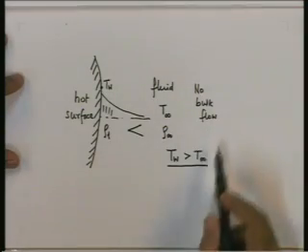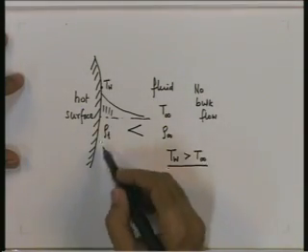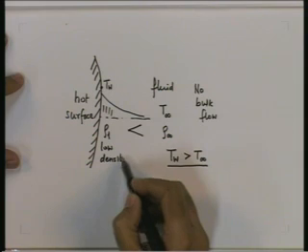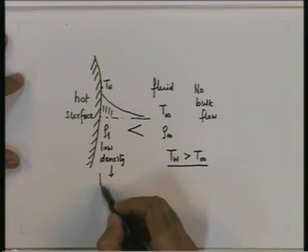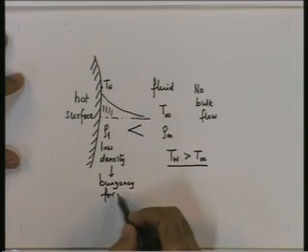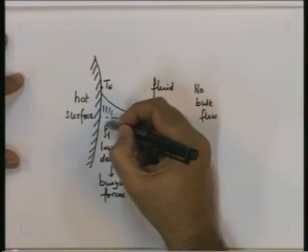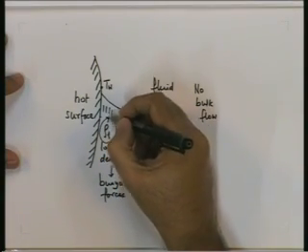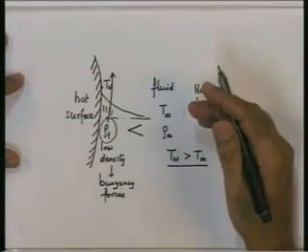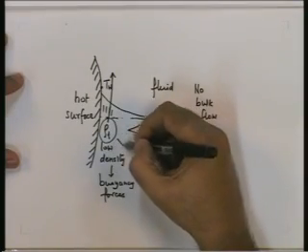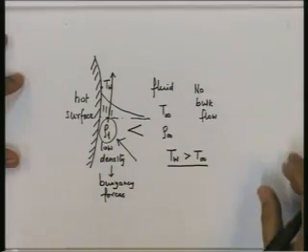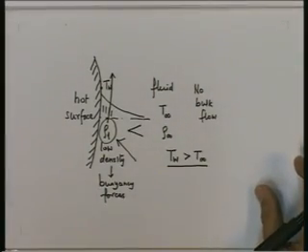So that means in this bulk fluid there is a zone of low density. This zone of low density leads to buoyancy forces acting on this, and hence this zone of low density tends to move up, thus setting up the process of natural convection. It moves up, is replaced by fluid from the bulk, and the process establishes itself as a process of natural convection.